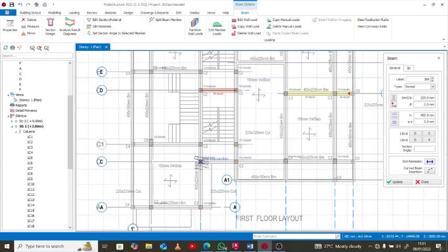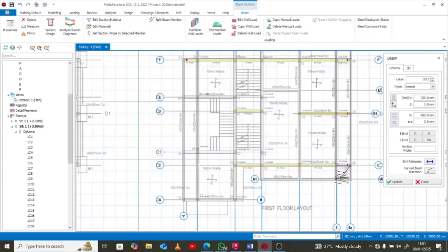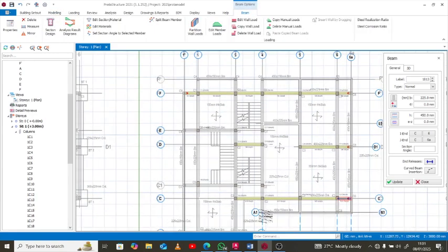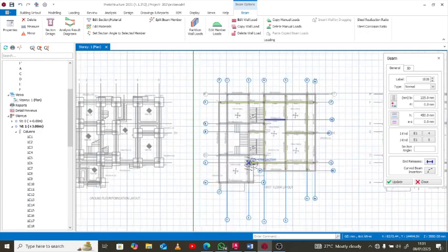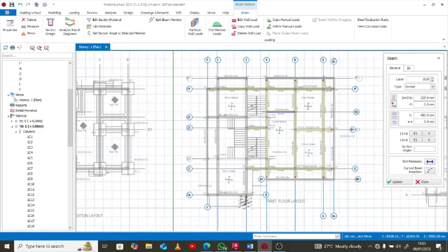So put that from here down to this place, and that's two, and from here down to this place, that's already cool. Then from here down to this place, I'm just trying to follow the principle of primary and secondary beam, and that's why I'm doing it this way, so that the support is communicated to the software appropriately.